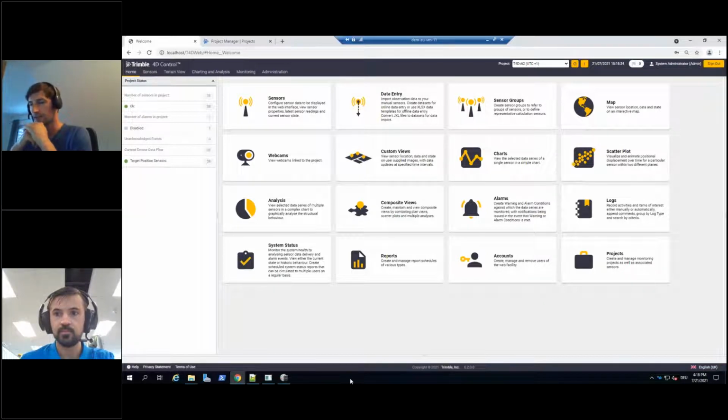You will also see it later on the maps page. I have configured about 40 positional sensors, prisms basically, that are close to the alignment and for which I get data from on a regular basis. This is all configured already in T4D server, and therefore I will start in T4D web right away.